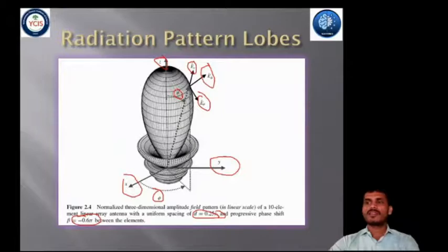Before going to the discussion, for an amplitude pattern of an antenna, there are 3 different electric components present, that is E_r, E theta and E phi, at each observation point on the surface of the sphere where r is equal to a constant, which is shown in the first diagram, that is figure 2.1. In the far field region, the radial E_r component for all antennas is 0 because it is the direction of propagation.